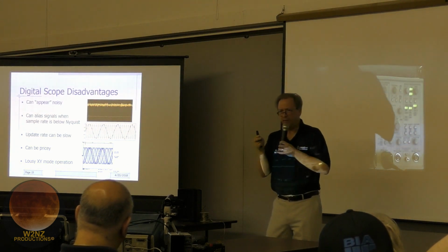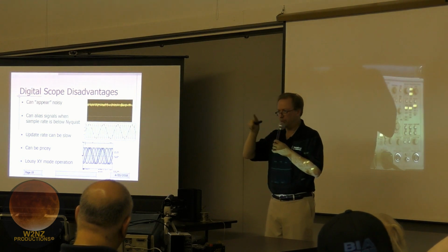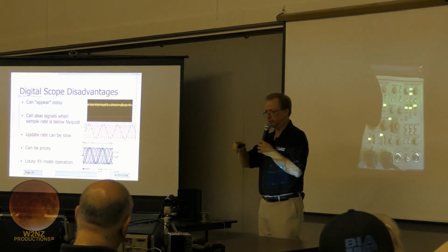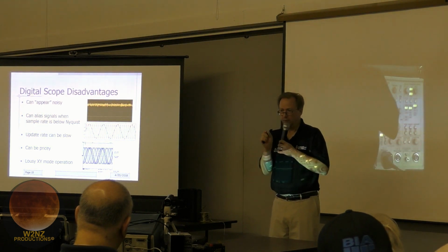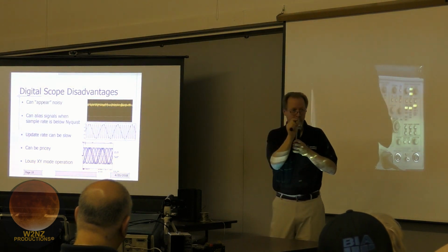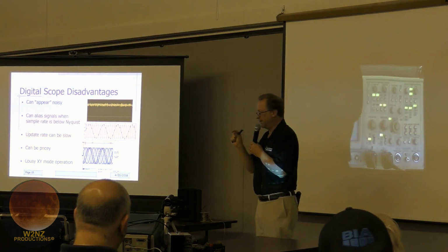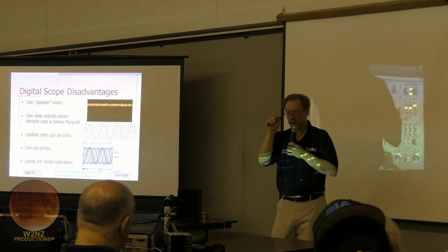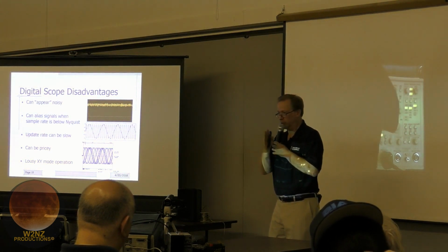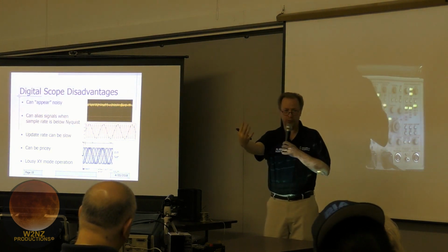Well, what you can do is you would have a very fast sample and hold circuit. So even though this sampler could be running very slow, maybe 10 kilohertz, 100 kilohertz, we're sampling very, very slowly. We're going to very precisely be able to capture a snapshot at an instant in time, like a very high-speed shutter on a camera. And as long as we know the timing relationship between that sample that you capture and the trigger, we can position it in the right spot on the screen. And then over time, you've built up a waveform.